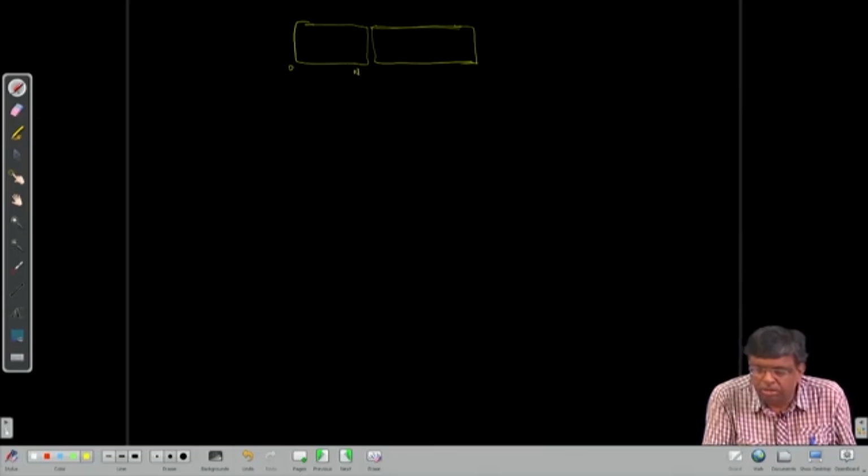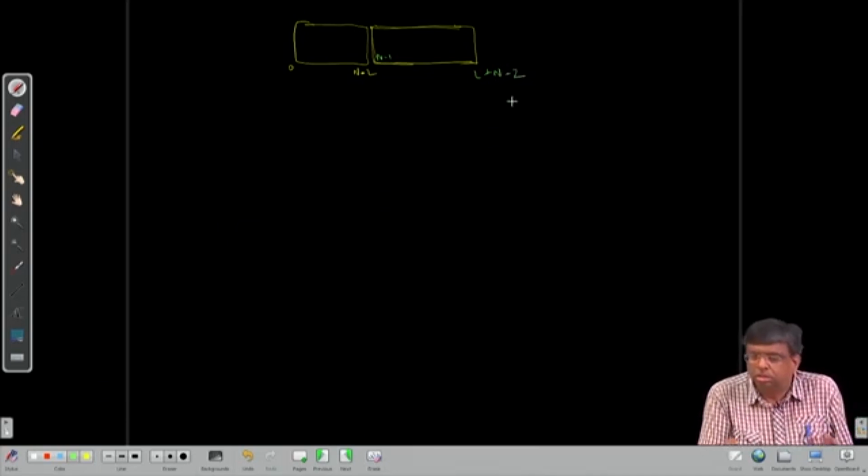Zero to n minus 2 is coming from the previous block, the overlap save part. I will discard the output from here, and keep from n minus 1 to L plus n minus 2. This we have already done.